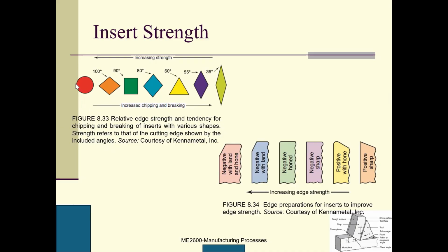So here, this is the wrong one, right? Increase the chipping and breaking. This one definitely is the weakest because it's the sharpest one. This is increasing strength. This one is the strongest one. This picture shows the edge preparation for inserts to improve edge strength.